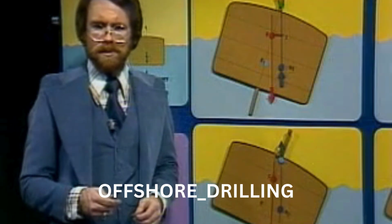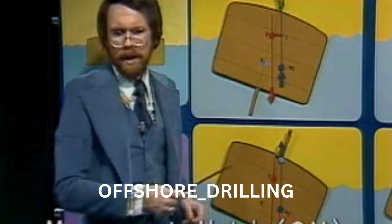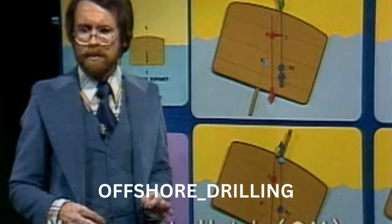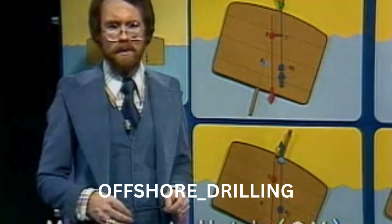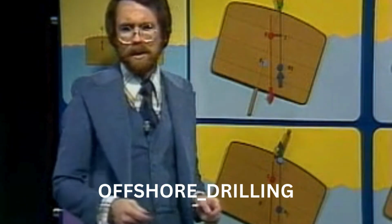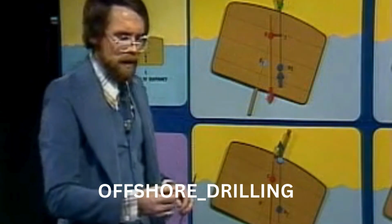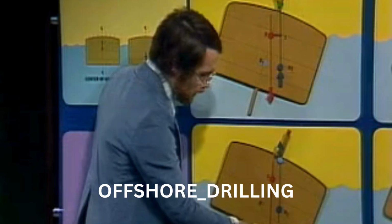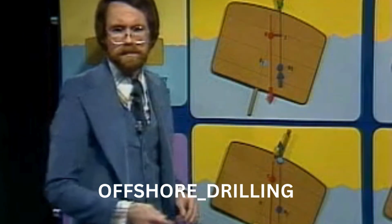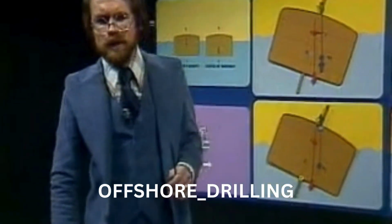This distance from G to M is called metacentric height. It is this distance from G to M that determines the initial stability of the vessel. To find GM, we first have to measure KM. KM is the line between the keel and the metacenter. We determine where the metacenter is from the hydrostatic curves.